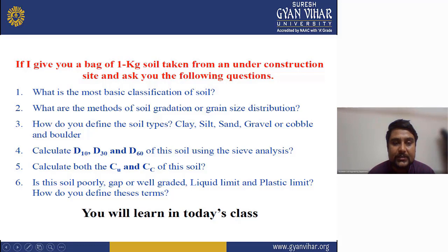Soil particle classification is given here, and these are the organizations which give methods of soil classification. Now we will see the grain size distribution, also known as GSD, and its significance: to know the relative proportion of different grain sizes. It is an important factor influencing the geotechnical character of coarse grained soil, not important in fine grained soil.